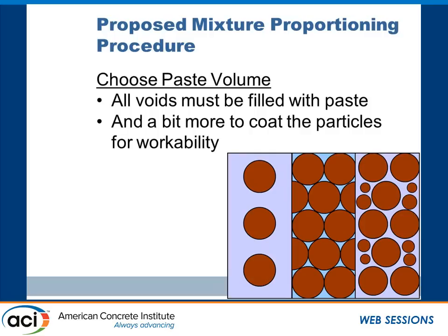So that's why we go with a graded aggregate system, and we make sure there's enough paste to keep those aggregate particles separated. 2 reasons. 1, the paste is the lubricant in the fresh concrete, keeps things moving. It separates out those hard, lumpy aggregate particles and makes them flow past each other. The other thing is that the paste is the glue. So at the end of the day, those aggregate particles stay together under whatever abuse and load we put into the system.